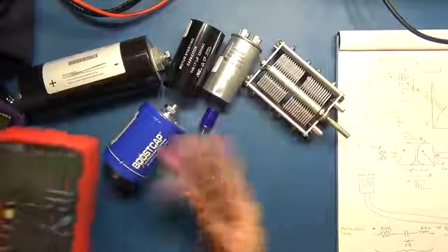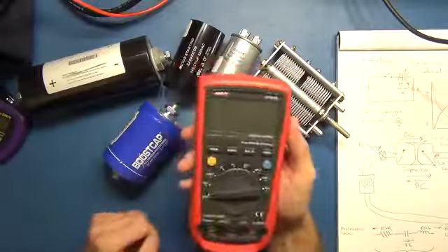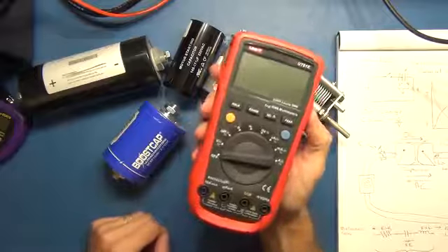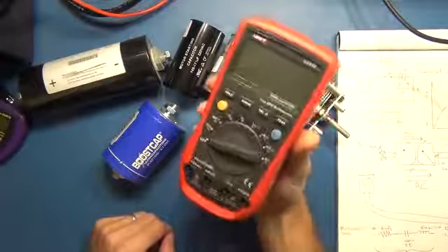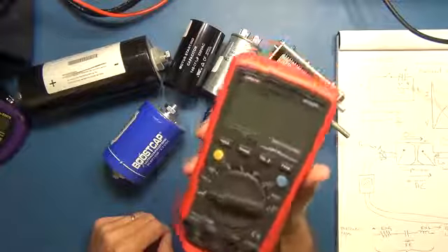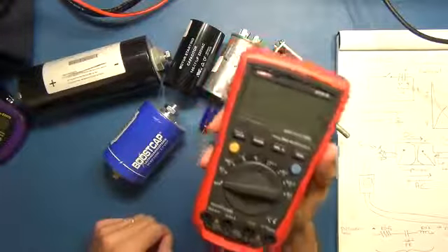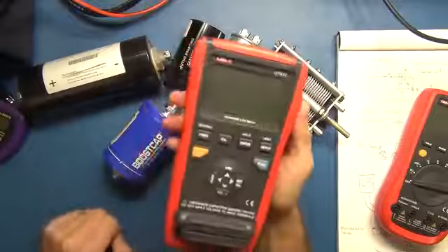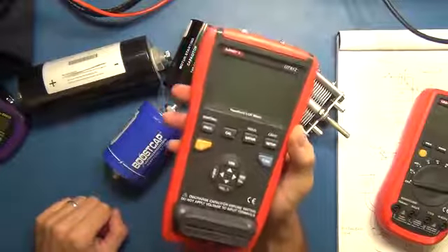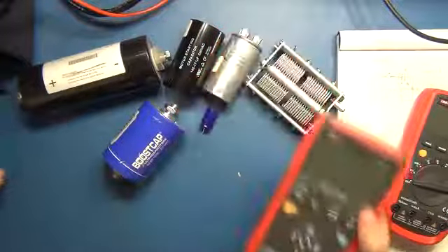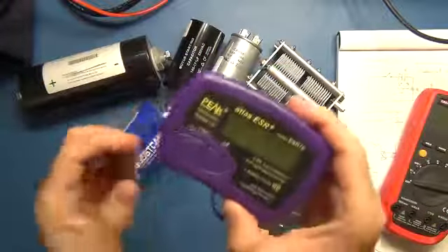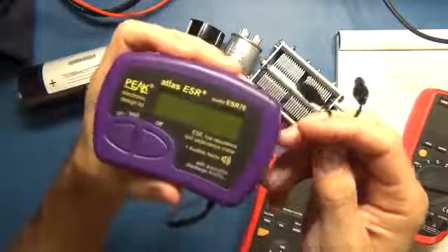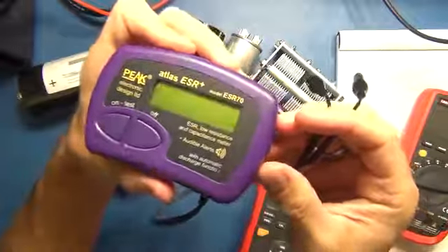What I'm also going to talk about at the end of the video, which I want to make you aware of, is that there are loads of different kinds of tools. The most common tool you'd think of using for working with capacitors is a standard multimeter. You can measure the capacity of a capacitor with a multimeter, but there are certain caveats and restrictions to that. To do things properly, you probably want an LCR meter, so that you can measure the capacity at a certain frequency and understand certain other parameters. And then you may specifically need an ESR, or equivalent series resistance meter, if you're trying to troubleshoot and see if a capacitor is still working correctly or not.